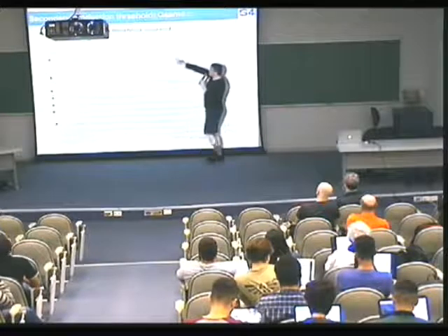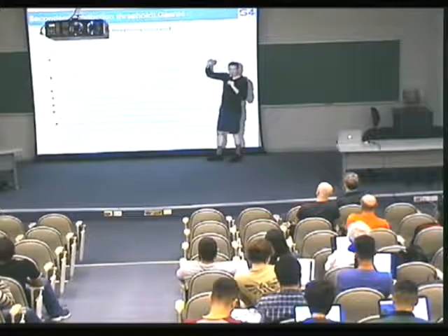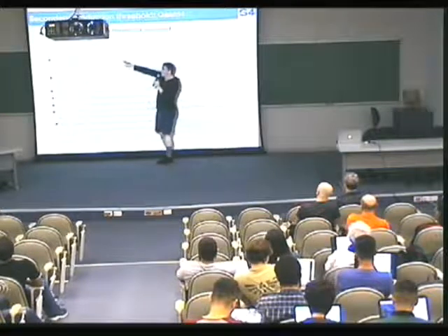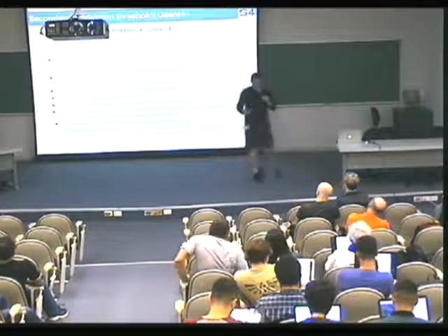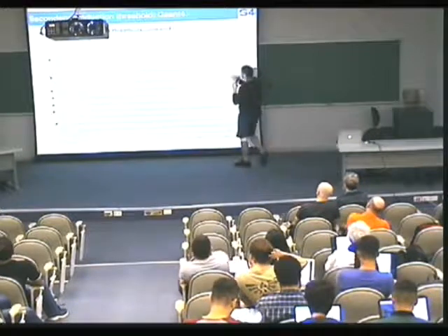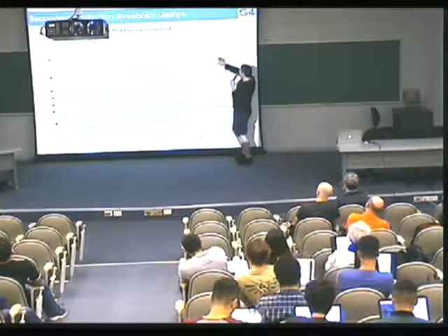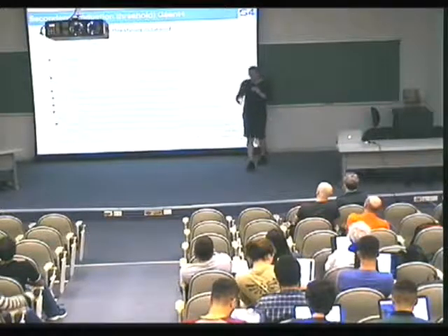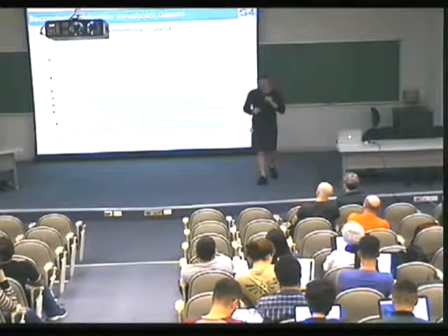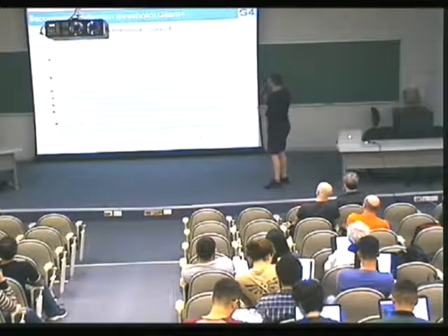And you can also specify it for one particle, because it will set a 0.1 millimeter secondary production threshold for electrons and for gammas as well. But if you want to set different values for electron and gamma, you can use this user interface command to easily set this for different particles.